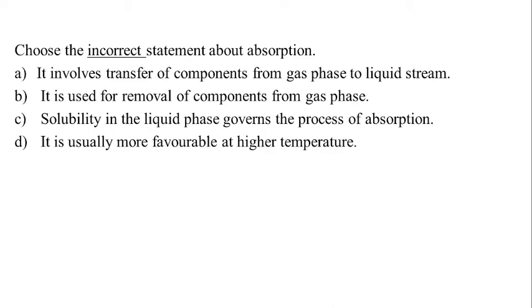So weak chemical bond formation during absorption will increase the loading of the solute in the liquid phase, that is in the solvent, many times, and at the same time it will also make it easier to regenerate the solvent by possibly boiling it off. So in fact, the choice of solute in practical situations, in most cases you will find that there is a weak bond which is formed. This is how the solutes are chosen.